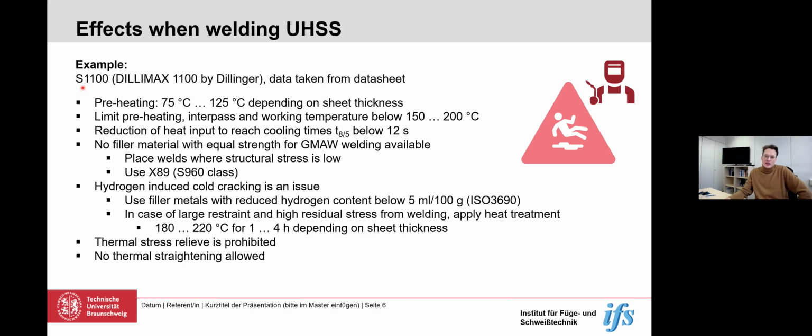Of course, when looking at this material S1100, we must say that we don't have a filler metal with matching strength yet. So what you do is basically you use the best filler metal that you have, and you just follow these recommendations. So there's also a recommendation on that. Best is to place welds where structural stress is low, and use the highest strength filler material that is available.